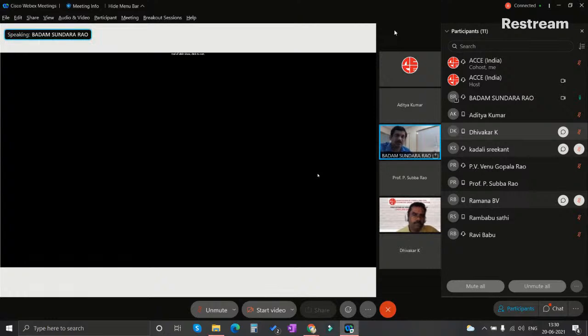That is during the formation and during the testing also, that we can observe the variation of the N values in sand. But in a particular site, as I just mentioned, the N value is almost constant throughout the depth of 7 meters, the depth of the sand zone. In these 7 meters, there is no variation in the N value. That is one of the peculiarities. Once we consider the N value of 7, it comes under the loose sand side. Then from 4 to 10.